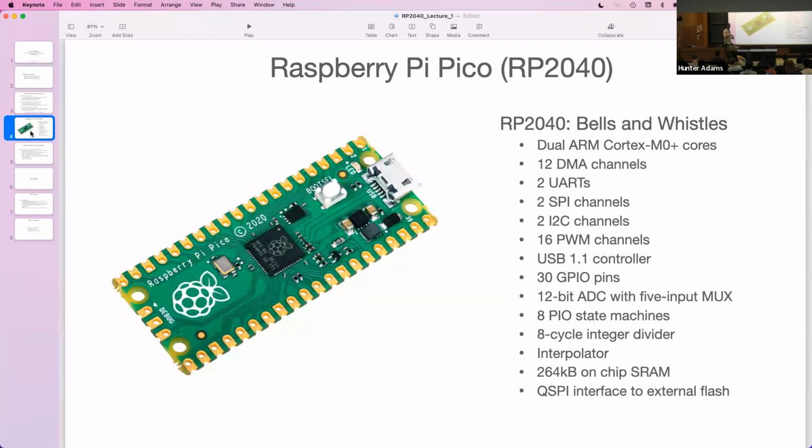It is, yeah, that is one of the uses for it. You can also do custom things with it. But I'll talk about the programming process for these things, and it is pretty unique as far as microcontrollers go. As I'll demonstrate, there's a little button on here called boot select. You push the button and plug it in, and the microcontroller appears on the PC or your laptop as an external memory device, like a flash drive, and you drag and drop the executable file onto it, and it's programmed. Pretty unique. But in any case, yeah, we'll talk about that.